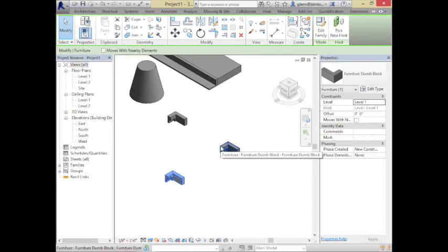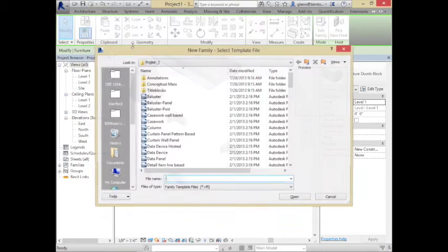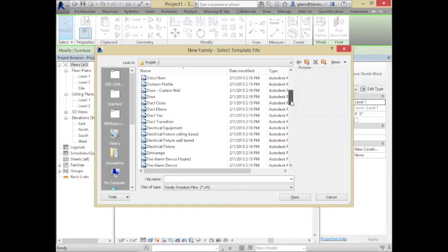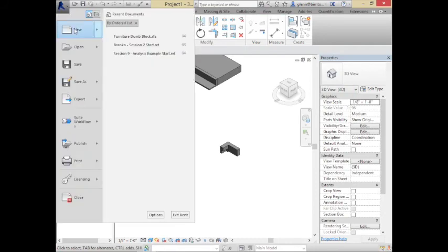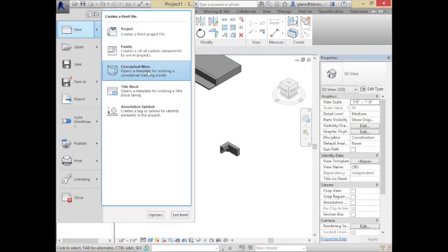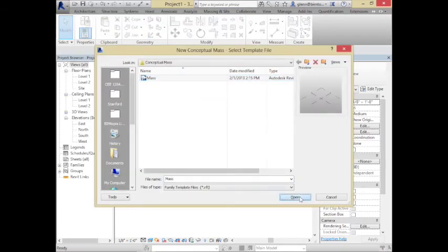Okay. Your question about this form that you want to put into multiple projects, it's just really another type of family. We're going to say new family. What you're interested in is something called a, actually, I'm going to take that back. New conceptual mass, a mass that has an arbitrary shape, like we created in the mass editor. For that, it's a special type of family. It's called a conceptual mass, but it's going to look the same. Say it's the mass piece.